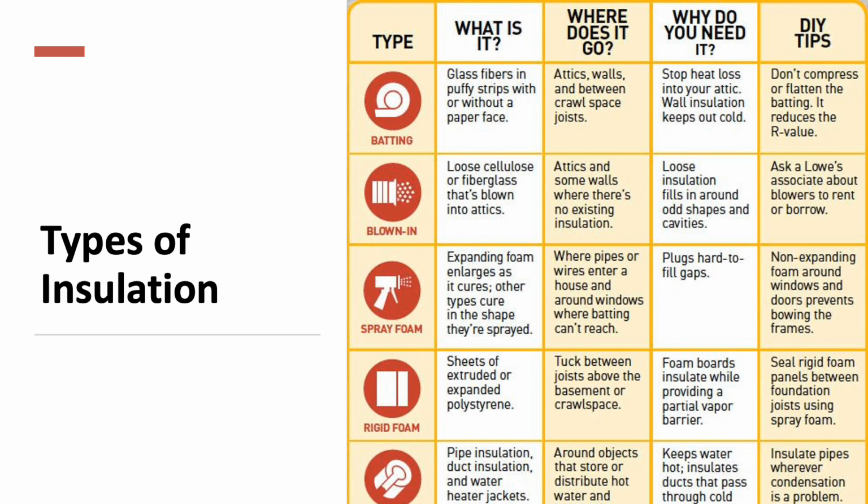You can have fiberglass insulation, which is a little bit easier to dry. However, if it's laying horizontally with fiberglass and the water causes the fiberglass to compact, you lose your R value. So you may have to take that out. So learn your insulations. If you don't know different types of insulation, take a trip to Home Depot or Lowe's or ABC Building and Roofing Materials and study these insulations. Get a sample of it, carry it home, and get familiar with it. It's not the same as residential.